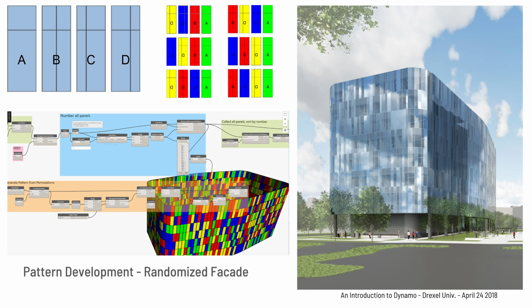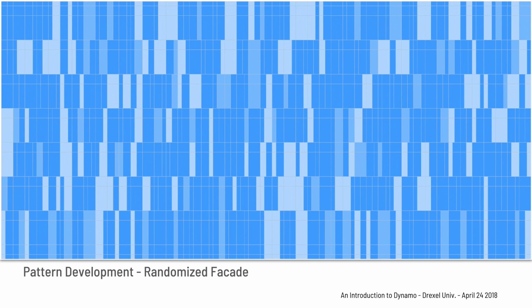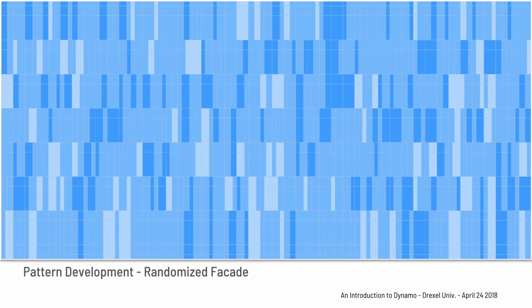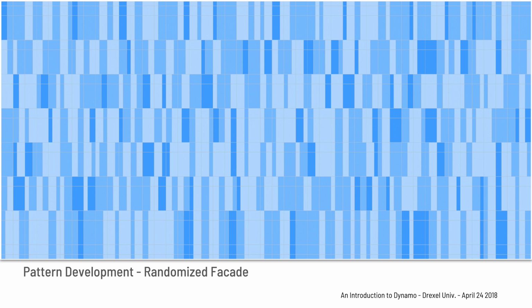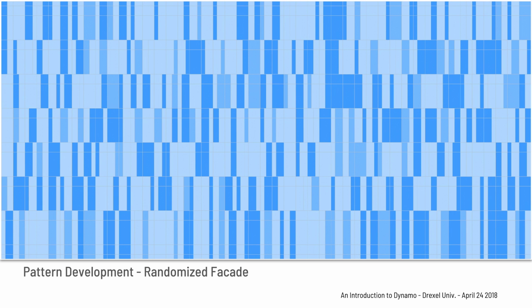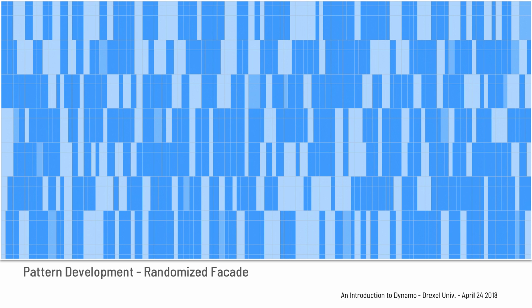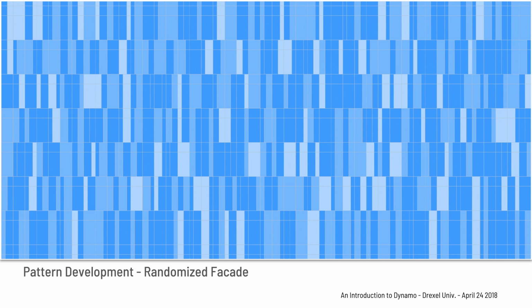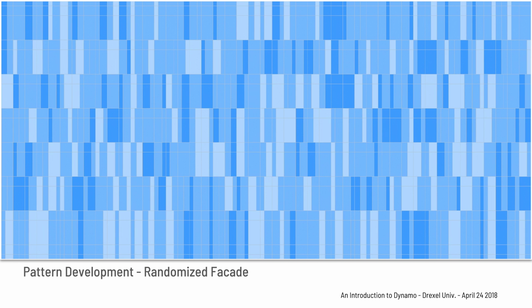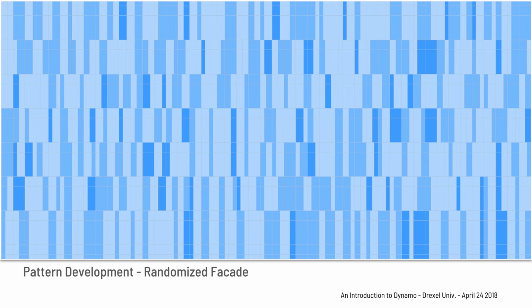This script also then applied the materials to the facade, so we were able to control for different glass types, and see what would happen if we changed the ratios between the different glass types without having to manually recreate everything. So this is just an animation that I made that cycles through different ratios of the 3 different glass types, so we can see from a very basic level what we think the correct ratio of all these materials is.